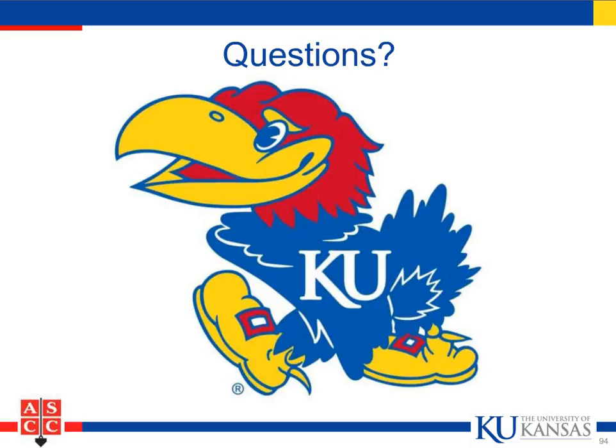What we drifted into a lot, Dave, is high-end interior floors that are only 2 inches thick, and the trend out here in California and Silicon Valley and Los Angeles has been to go with as few joints as possible. So our hat trick has been to try and produce as much of a crack-free floor at 2 inches thick in a seamless fashion where we don't have any joints.